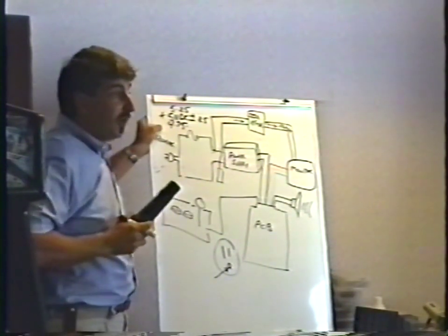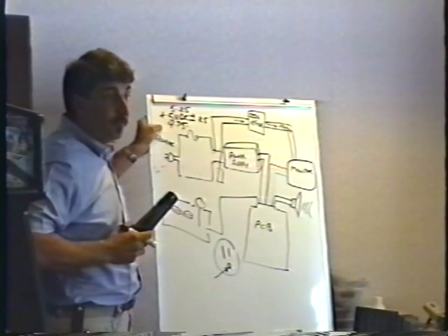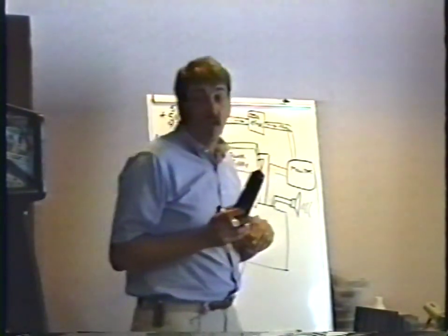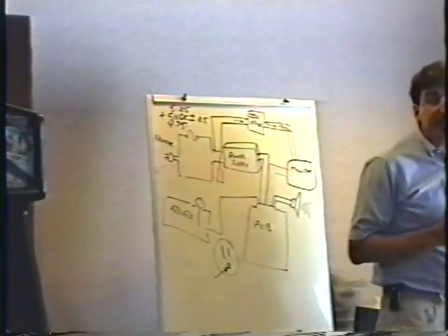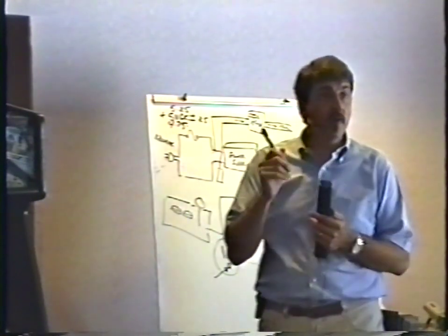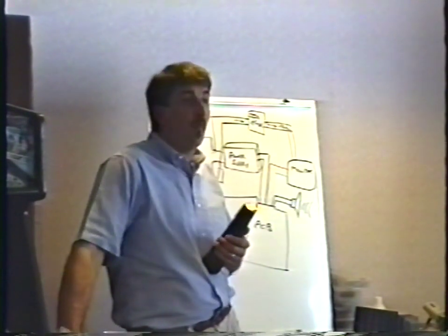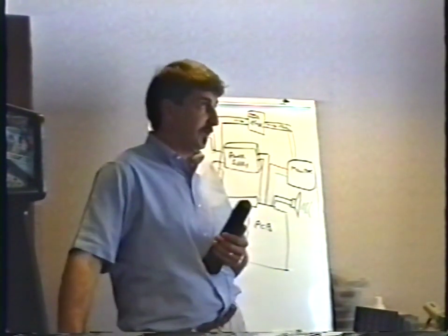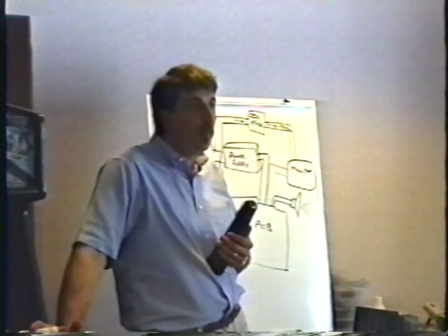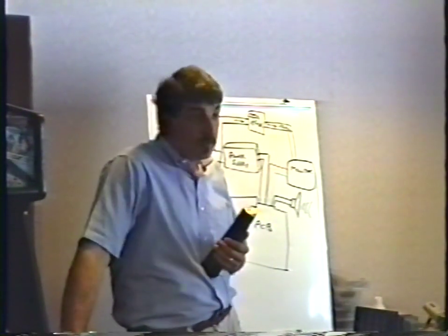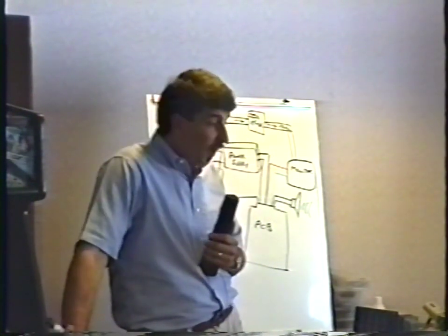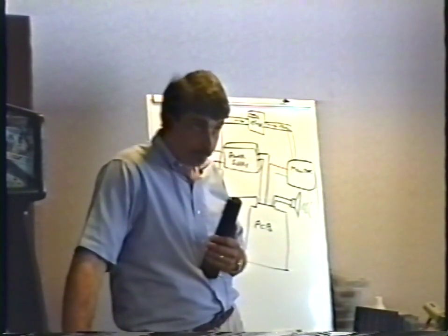Quite frankly, I find that almost nothing works properly at 4.75. Especially like Sky Shark here, it'll crap out at 5 volts even. At Area Amusements, we set all of our games to 5.1 volts. We set the power supplies to 5.1. Some people say 5.17. Well, whatever. 5.1, 5.15, something like that. We just have found that we have far fewer problems that way.